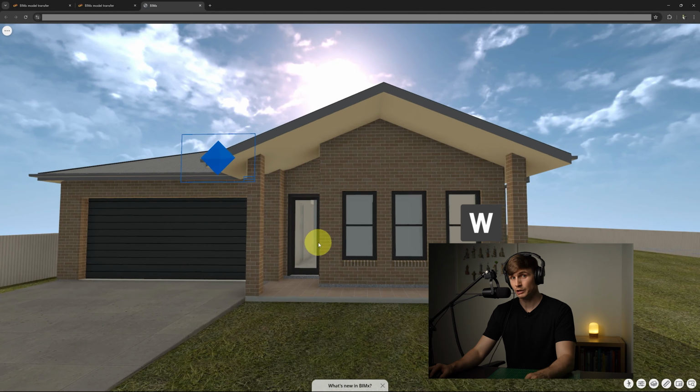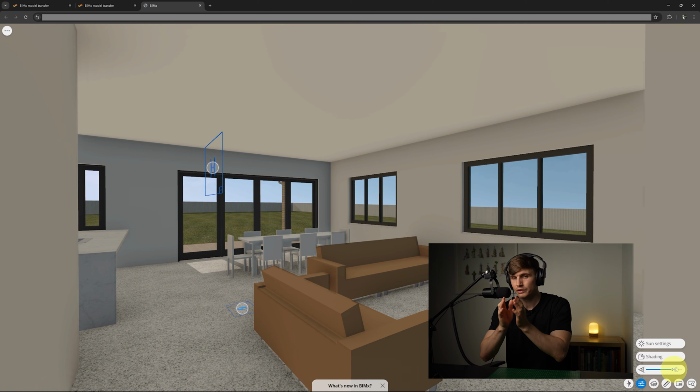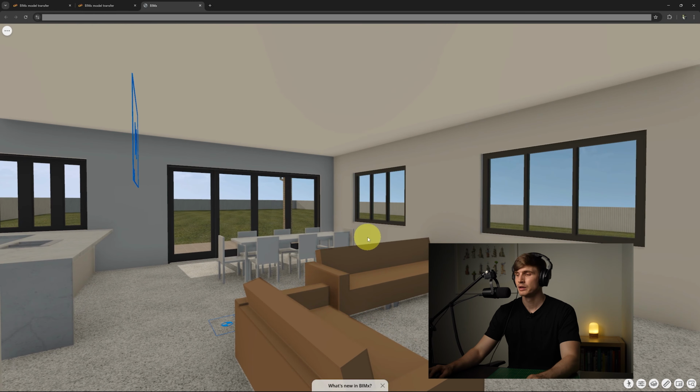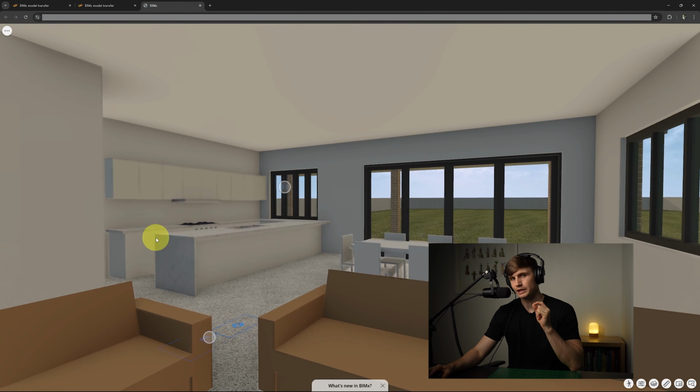through our 3D model. When we're in the 3D space, if we want to expand our view, down this bottom right-hand corner, if we go to Field of View and we increase it to the right, it's going to increase the amount that we can see. This typically makes it easier to navigate in tighter spaces so that we can see more of the internal view.